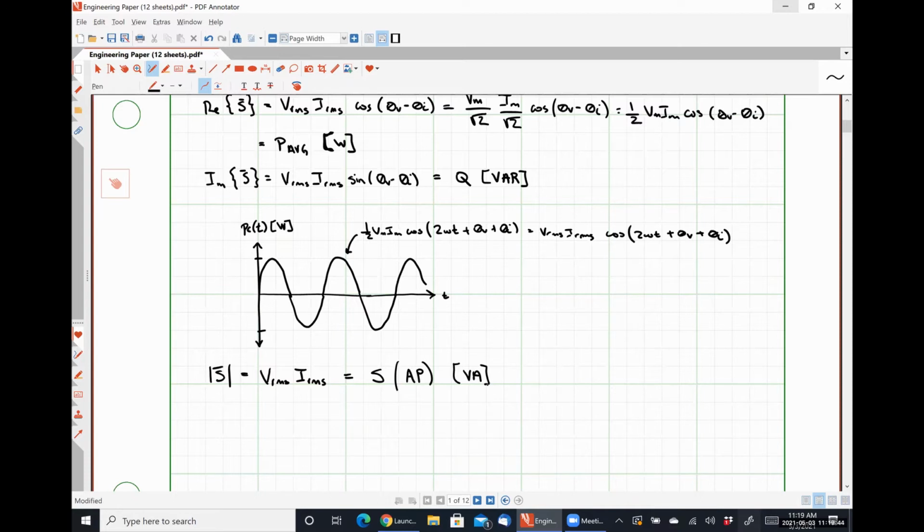Okay. So ampacity is the technical term for the amount of current a wire can safely handle, okay? So for the wires that feed the plugs in this room, they have to have an ampacity of, let's see, what's 15 times 125%? 15 plus 1/4 of 15 would be around 18.75, something like that. They have to have that amount of ampacity to safely carry currents. It's at 125% because that's what the National Electrical Code tells us that we have to do to maintain a proper safety factor. The ampacity depends on both the material of the wire. So in most modern systems, it's just copper wire. It might be braided or stranded or something like that, but it's usually just copper wire. And it also depends on the insulation material.